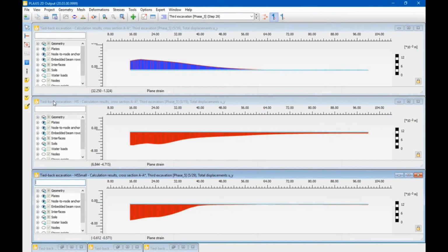This is a typical result of Mohr-Coulomb in excavation. Mohr-Coulomb is a purely elastic model, and in this case, we excavate, so we unload the soil next to the wall, because we reduce the horizontal stresses, and we just get a swelling. Because we get an elastic swelling because of the stress level decreasing, and because of the elastic swelling, the volume increases, and the volume increases a lot more than that little bit that the wall moves. So the soil moves up in Mohr-Coulomb, which is not what we see in practice. So Mohr-Coulomb is really not doing so well here.